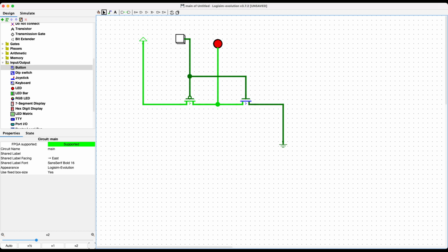But basically, the way that they work, you can think of them in a primitive sense as just being switches, just like the light switches in the room. The switch can either be on or off. Now that's not entirely true in actual electronics, because when we say on, we mean high voltage, where high is defined as whatever we're powering our thing with. In an Arduino or a Raspberry Pi, it's 3.3 or 5 volts. In modern processors like Intel stuff, it's just over 1 volt.